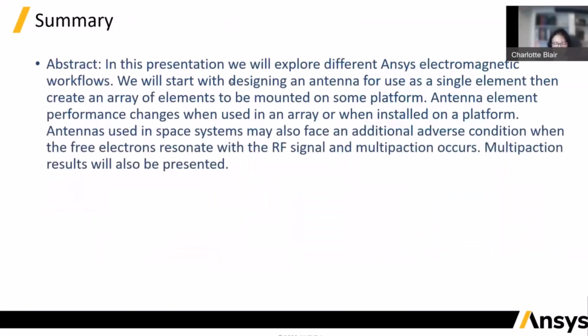hopefully, as I said, what we did was design a single element. We used the ATK, the antenna toolkit, to design it. I created the array using 3D components and the finite array element. I mounted it on the satellite. I used STK and used situational awareness, and I went from the LEO orbit down to Ansys headquarters and showed you Multipaction. And we did see a course that we do offer at Ansys and a free download.